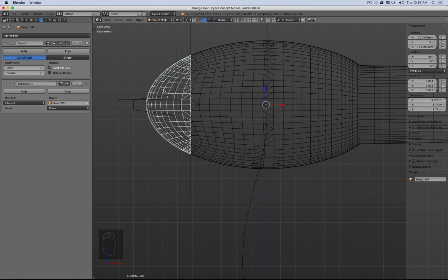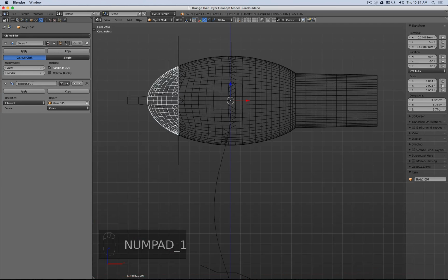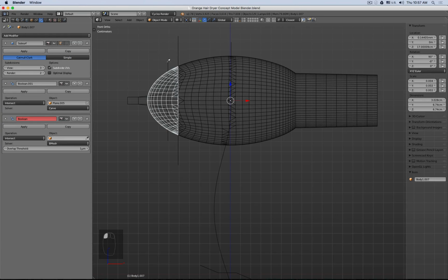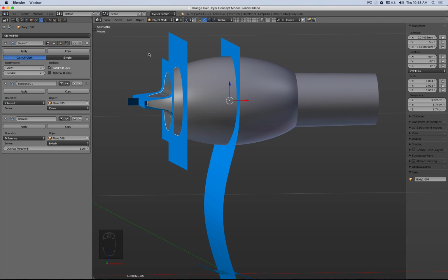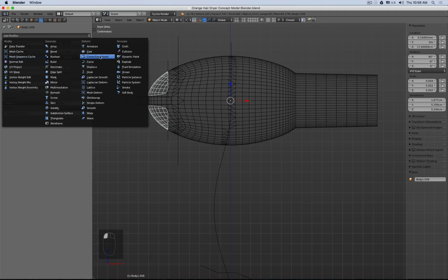Now I would like to have these areas cut out. So Alt, no, actually not Alt D. We will add a boolean and add just this one, but difference, there we are, perfect. Alt D, and then here intersect, and the first one we can remove. But this one is actually flush with the surface. This should be recessed. So we have to use our displacement modifier.